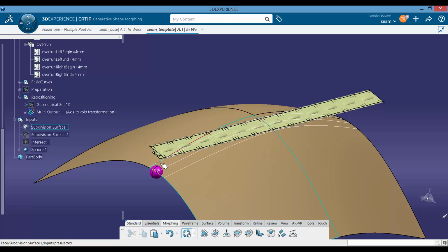Blend was first idea to do it, but as you can see it contains a lot of points, so technically you could do curve smooth on it and try to blend it, but unfortunately if the curvature of the reference surface is relatively strong, this blending won't work.